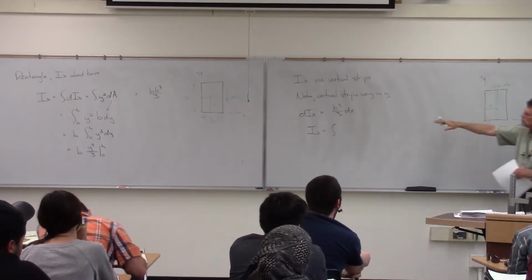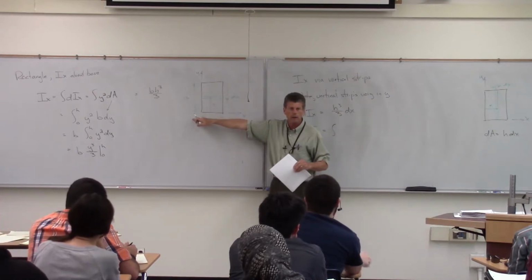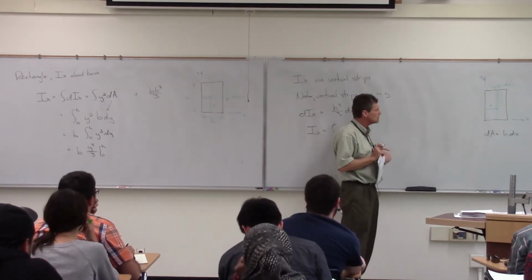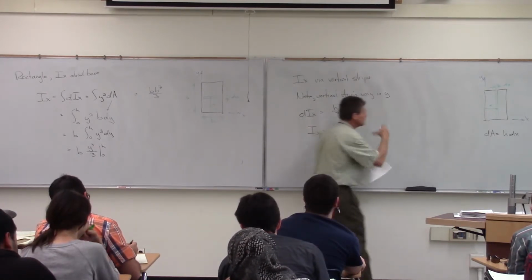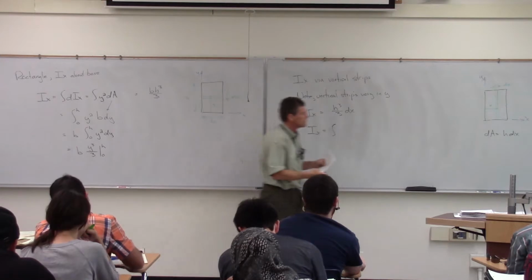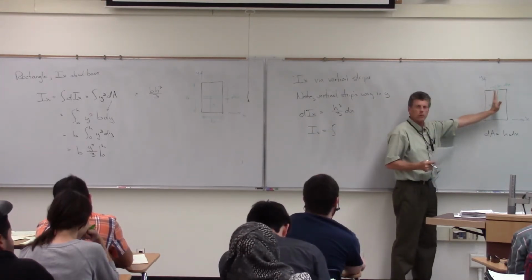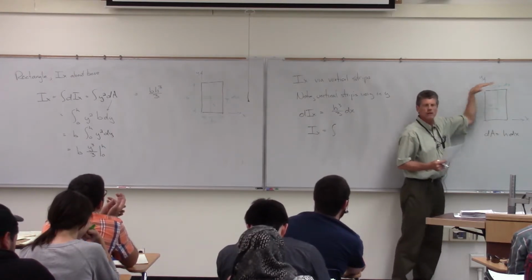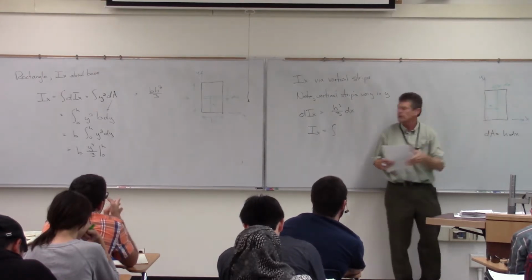So what I'm going to do is take advantage of the fact that I've already calculated that here, but it's just really tricked for integration to get it to integrate properly. But it's recognizing the fact that that strip, if I was going to do it about Iy, that's the way I want to do it. Perfect. But in terms of Ix, since it varies in that y, I need to capture that variance that's going on there.